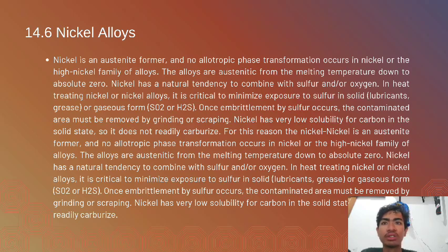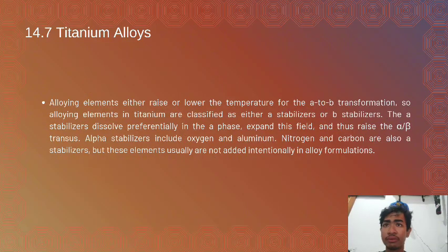For this reason, the nickel chromium alloy, notably Inconel 600, is used as fixtures in carburizing furnaces. The most common heat treatments are stress relieving, in-process annealing, full annealing, solution annealing, quenching followed by precipitation. 7. Titanium alloy.